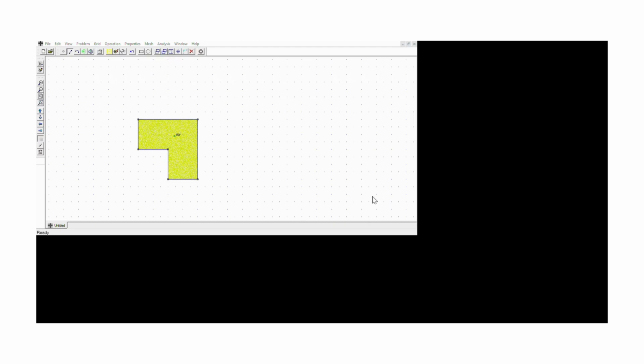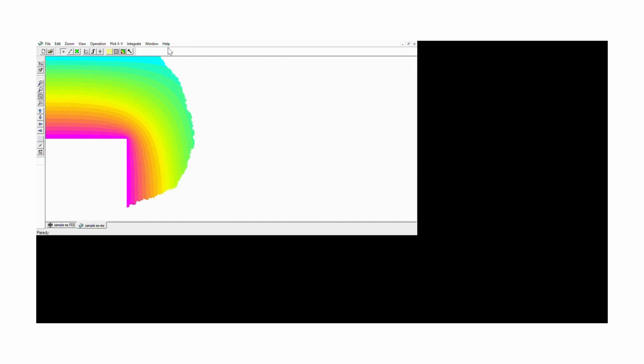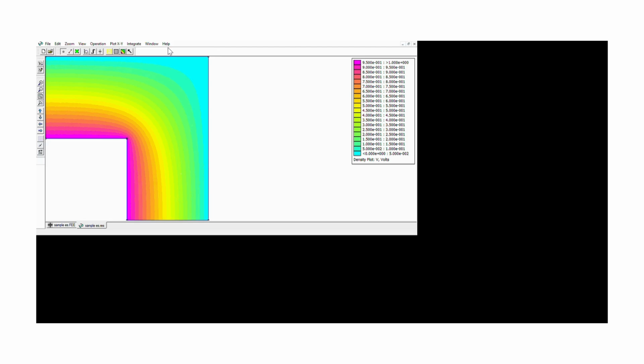So now a mesh with 5484 nodes has been created. Now I have to run and execute it. After creating the mesh, to run and execute, I have to click this, and now I have to click this. So this will give you the number of nodes and the voltage level from this point to this point. See, this being 0, you can see the potential to be 0, and this being the higher potential, it is showing the higher potential of 1.